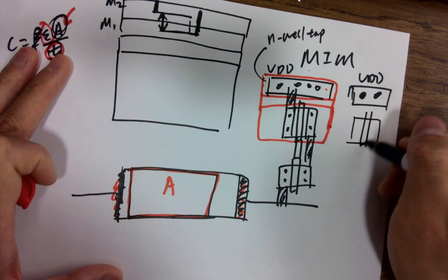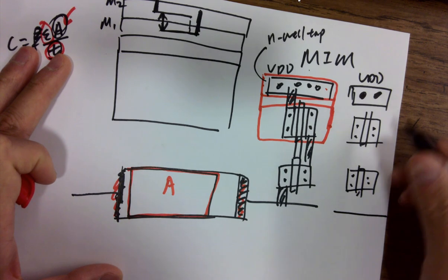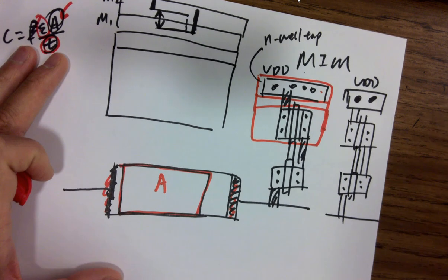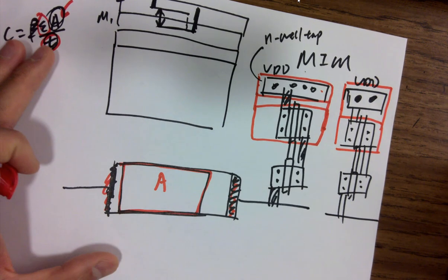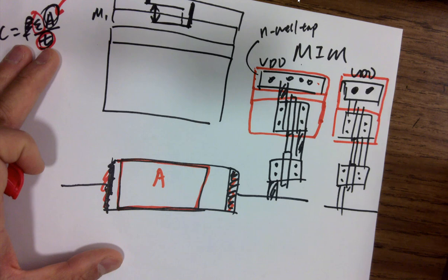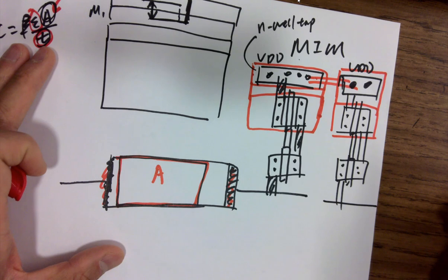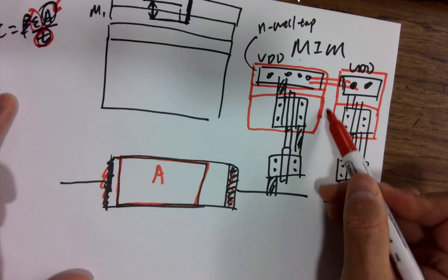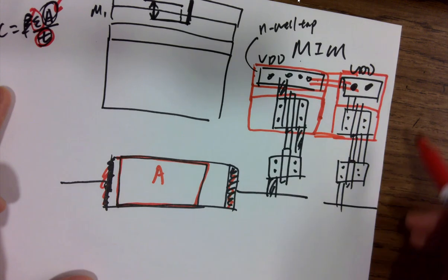I'm just drawing this fast, okay? Is this correct? Yeah, well, they're connected, right? So at least you need to short the VDD together. They are both VDDs, right? Yeah. What else? They are both VDDs, and the N-well taps and N-wells are both shorted to VDDs. Why do you want a gap over here? The body effect? No, you don't want a gap. It's the same N-well. Okay.